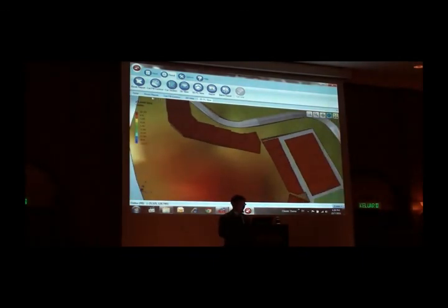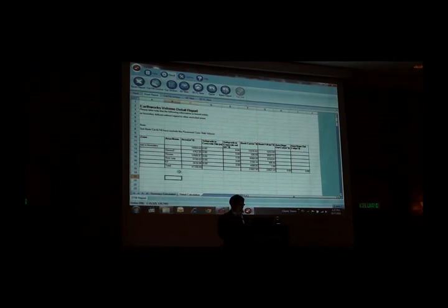That's all. Come back to the Excel report. So we can apply the swell and shrinkage factor to get the bank cut and expanded cut. So bank cut times 1.1 factor gives expanded cut of 30,000 something. And then the fill. So the export or import: if the cut is more than fill, that means export, it's positive. If negative, that means import. And we have the detail calculation, which depends on how many groups of platform names we put in. So divided into groups.